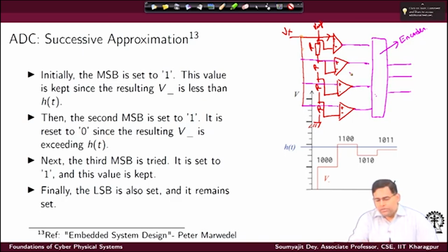What is the advantage of this scheme? Definitely it would work in a flash, right? Because there is no requirement of multiple clock cycles or anything. So that's why this has a name. It's called flash A2D converter.